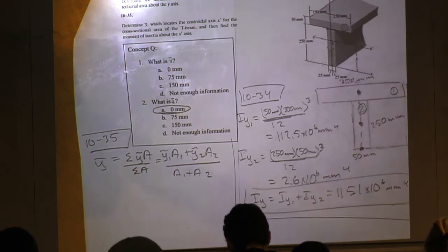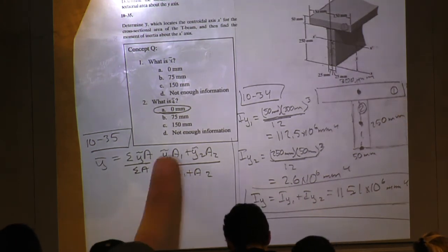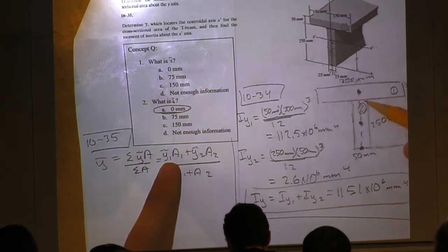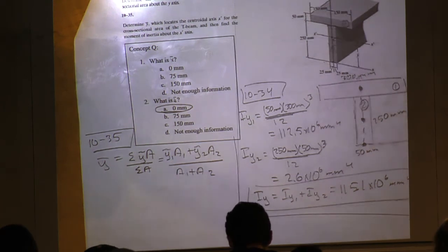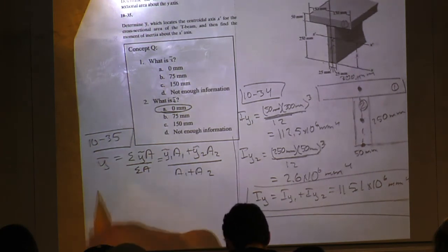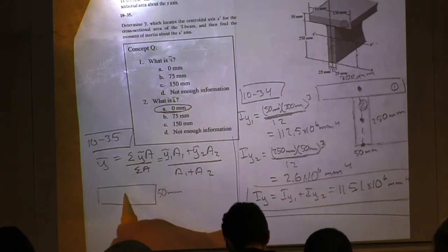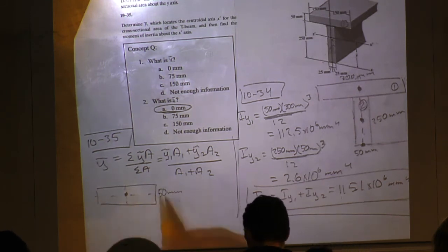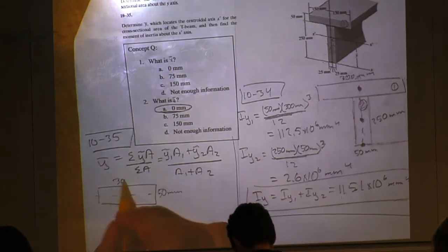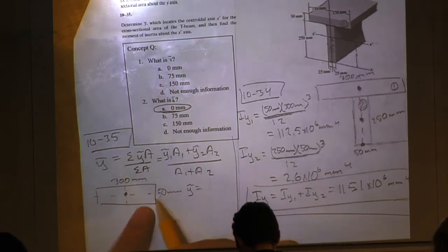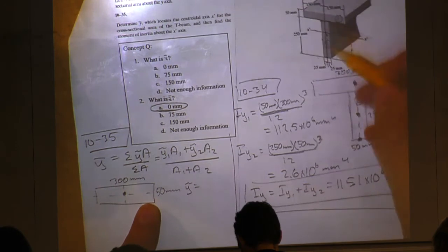Now when we're looking at these little y tildes is when our height is going to matter. So our y tilde for this first shape here will be half of this height plus the initial height, right, which is 250. So our y tilde for 1 is going to be in the center. And then that's 300. Y tilde is, remember this, 25 plus that 250.